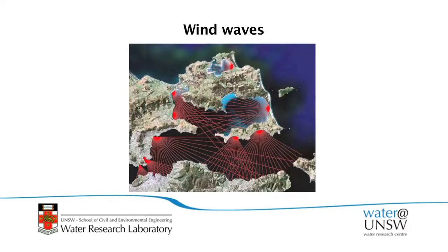As well, that's open ocean swell waves, but also a lot of sites aren't exposed to that at all. An example might be some of the shores of Moreton Bay, where you're only exposed to local wind waves, which is just the wind blowing over the water. So the ocean swells can't really get in there with any real size. So here's an example of how we'd work out the wind wave climate to design for at any given site.